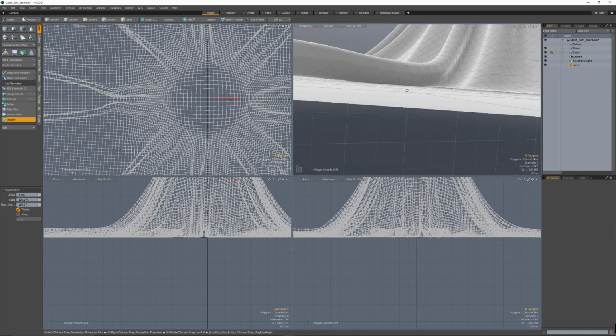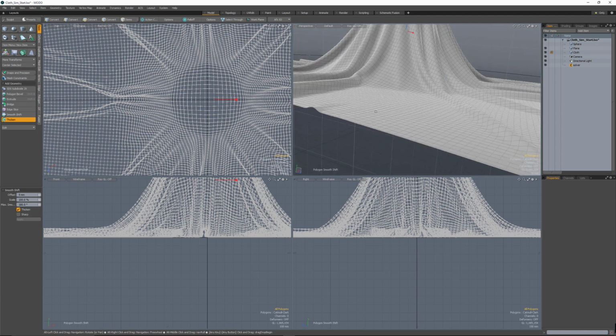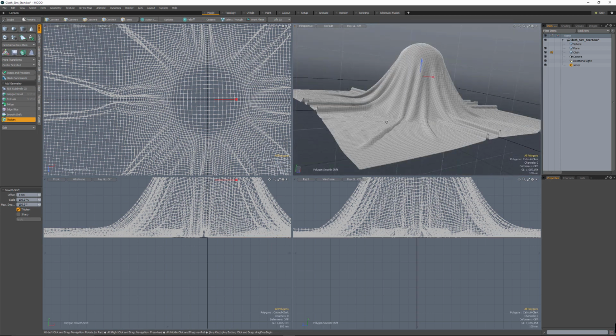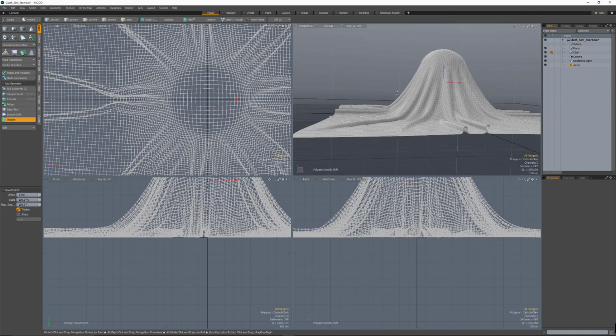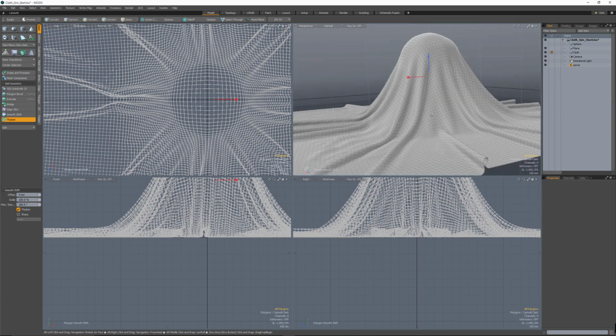You want to check areas like this where we've got some tight creases, and everything looks okay, so we're probably all right. But if you have this set to a lower amount, you may need to increase your max smoothing to 180 degrees to make sure that you don't get any kind of strange crossing over polygons, and things will pop and just look in general not right.